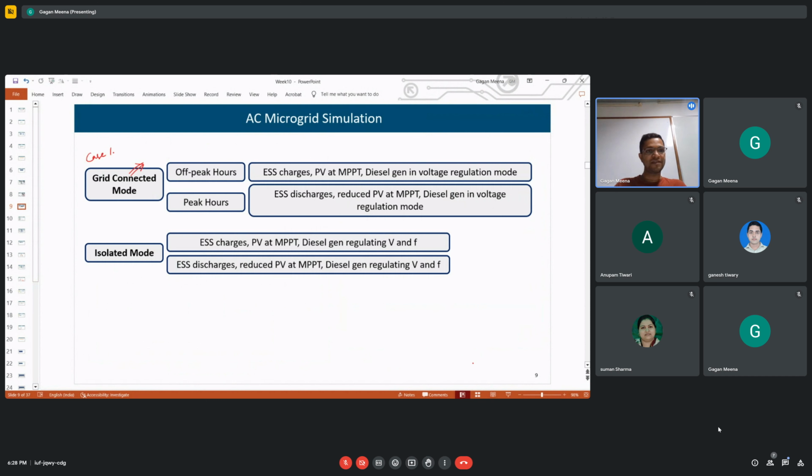The name suggests series, but both may be used for voltage correction, series and shunt. No, series will be used to check the current. We discussed the Faraday effect. Voltage was increasing, so we were using a shunt reactor, right? So shunt we are using for voltages.